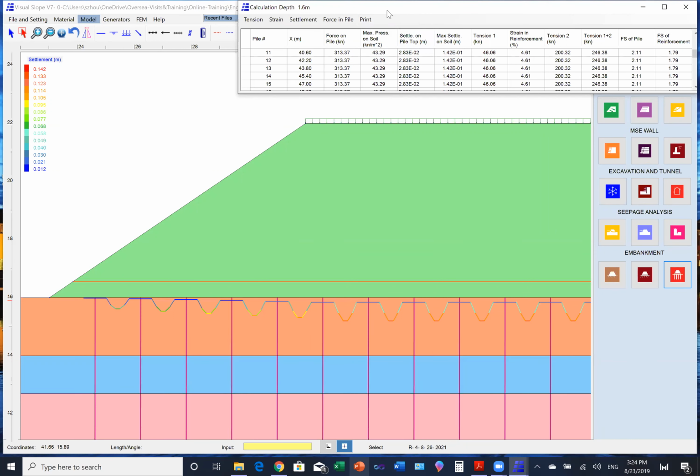It will also give you the arching height, and when we design that, the embankment thickness must be at least 3 times the arching height. Otherwise, it will experience settlement on the top of the embankment. You will see some dimples on the top. So you must have at least 3 times the